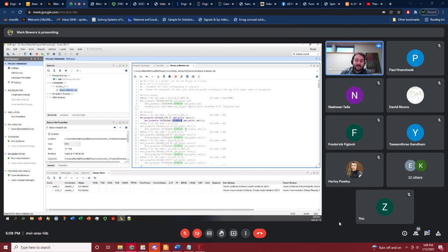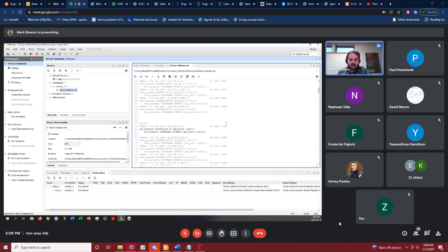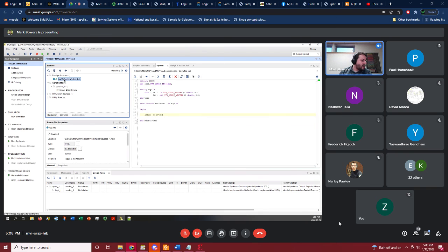If you have these commented and you try to compile, it'll get about two thirds of the way through and say, I don't know what SW0 is. What are you talking about? So make sure those are uncommented. We've got our simple example here, and we are going to go ahead and run.